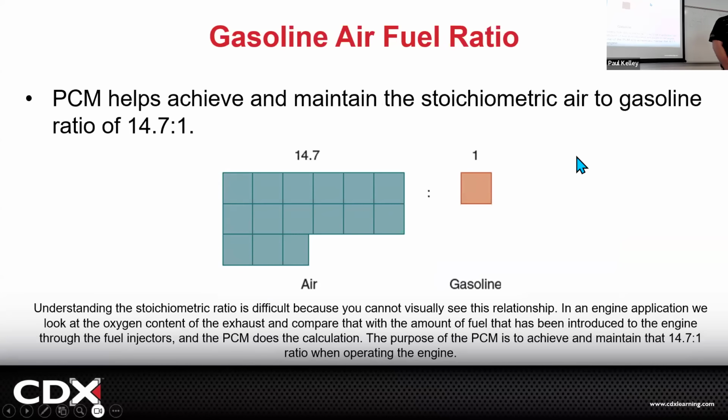All right. So when we get into this a little bit later, what you got to understand is that for gasoline, the correct air fuel ratio is 14.7 parts of air to 1 part gas. Now we're assuming it's good quality gas, right? So now we're good on what gas is, and it shouldn't have water, and it should be like 90% gasoline and 10% ethanol, and the gasoline should have the additives. Well, if all that's true, to make good clean combustion, we need 14.7 parts of air to 1 part of fuel. But understand this, it's not by volume though, it's by weight.